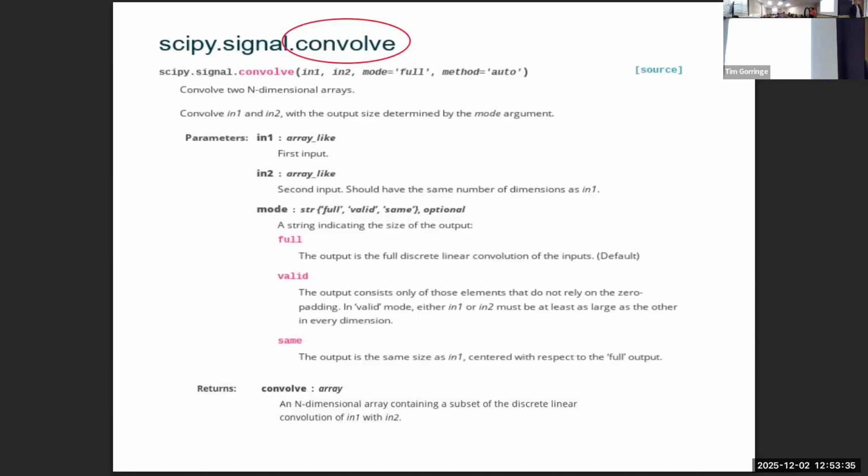Okay. So those are the time domain filters that I wanted to introduce. Big differences from the RC filters is that these are convolving filters. They just depend on the input. They don't have any feedback from the output. Another big difference is that in the recursive filters, the RC filter, really we were just taking one input sample, the current input sample, and the prior output sample, and combining those. It was kind of simple in terms of the calculation.